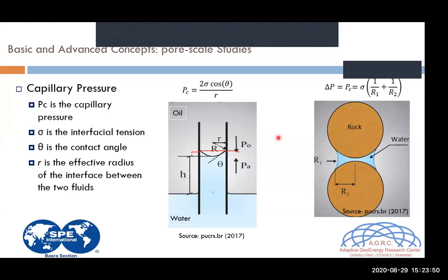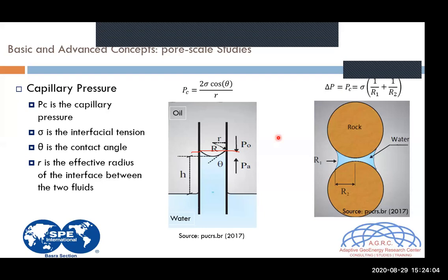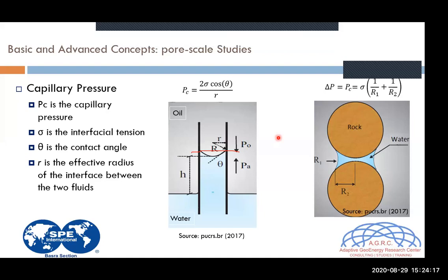So really simple equation, just to keep you aware that we are dealing right now with the capillary pressure, the difference between two different phases, because we're trying to understand, or at least try to simulate as best as possible the interaction between the two fluids in a pore system that can provide you later some graphs, for example, for PC curves, some KR curves, and all of them are related with the pressure differential here that we are discussing.